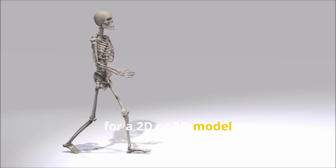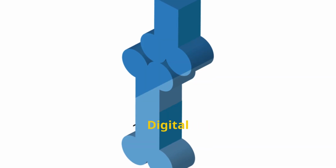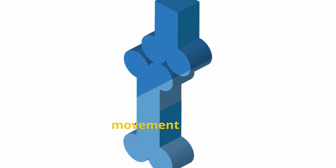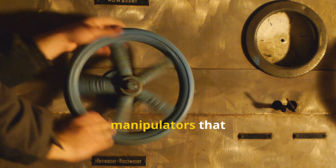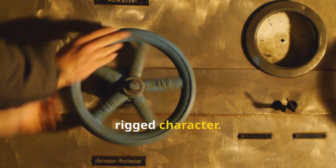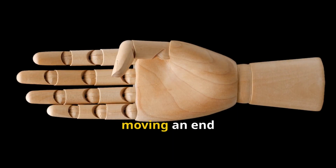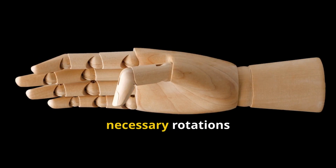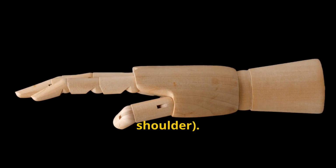2D or 3D model to facilitate animation. Bones, joints: digital representations of bones in a character's skeleton around which movement pivots. Controls: user-friendly handles or manipulators that animators use to move and pose the rigged character. Inverse kinematics, IK: a rigging technique where moving an end effector, for example a hand, automatically calculates the necessary rotations in the connected joints, for example wrist, elbow, shoulder.